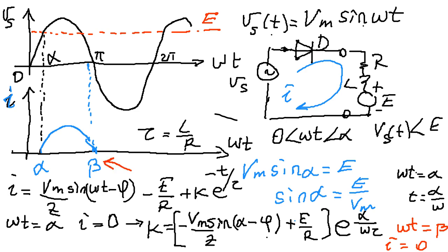Okay, so this current is not sinusoidal. It has a sinusoidal component, it has some kind of DC component, but that constant value is exponentially decaying, so it is reducing while time is running out. So you can obtain the beta. You cannot solve that equation by hand. Therefore, it is necessary to solve it by iterative methods.